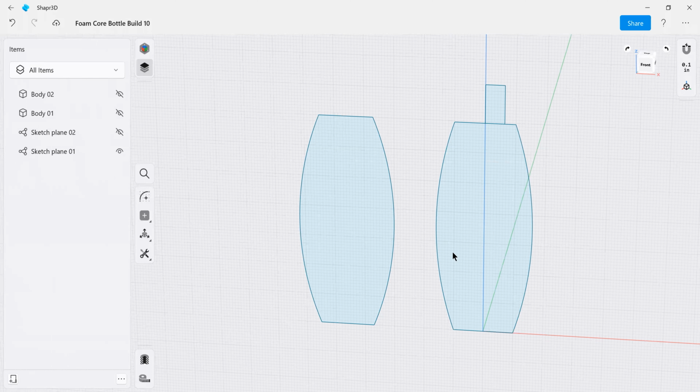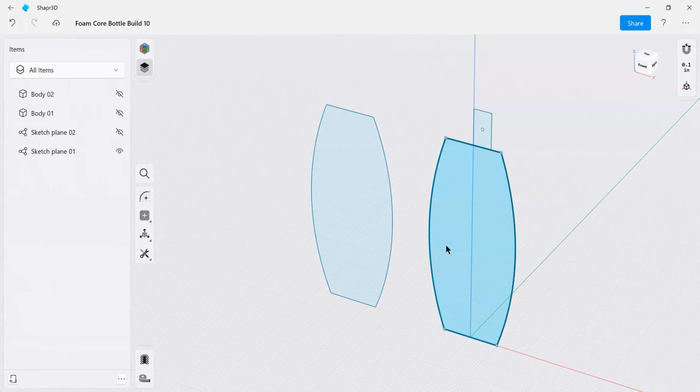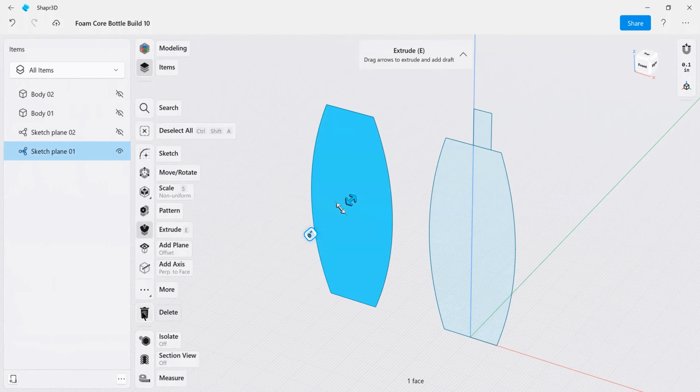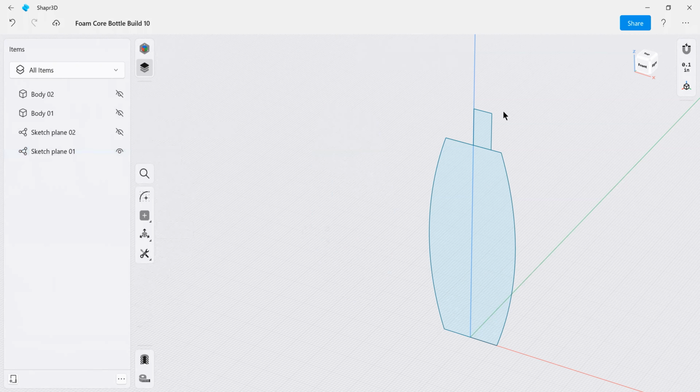I'm going to take this and extrude it, make it a thick, solid body, and then I'm going to trim it with some other sources. So let's go back to this one. I'm going to delete this because it's exactly what I have here. We don't need that anymore. This little rectangle is literally just the rectangle tool, and I built it on top, and it's half the width of my closure. And I'm going to revolve that. So I'm going to show some revolving, extruding, and then a Boolean operation and some radiusing. So this should be pretty straightforward.